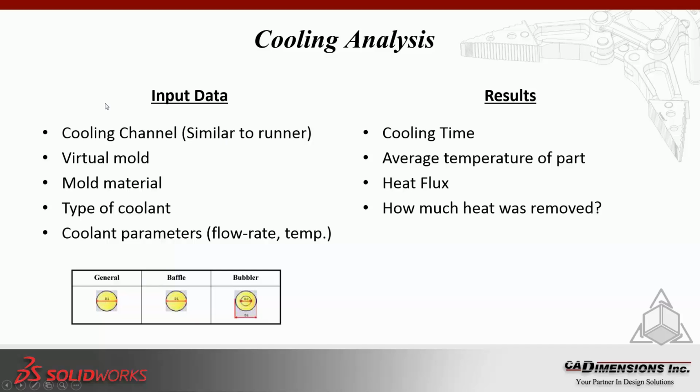So what type of results can you get from this input data? Well, one is the cooling time. Very important, we need to know how much time it takes for your part to cool down. Average temperature of part, heat flux, and really to answer the question, how much heat was removed. So it might be too much, might be acceptable. You'll be able to see that.